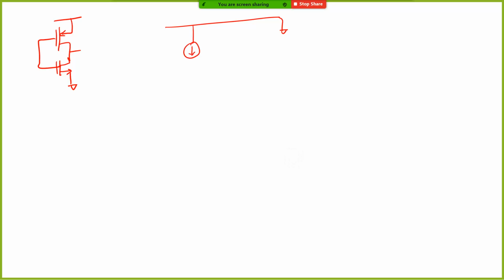Let's say this is your VDD, which is an AC ground. This transistor is in saturation, and this is nothing but gm Vsg, as I mentioned in the last class. For PMOS, you just switch the subscripts. That is enough. And this is r0. The body effect is not in the picture because for both transistors the bulk and source are connected. Here you have gm1, this is gm2, VGS here, and you have r01 and r02.